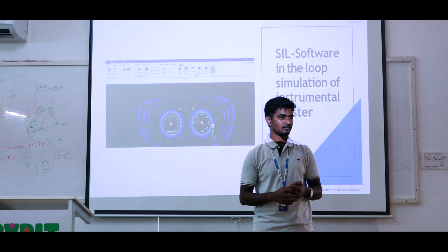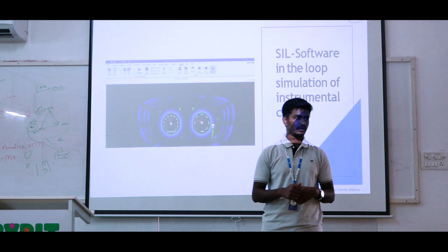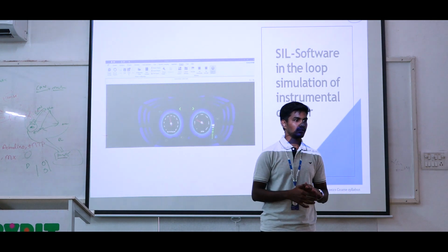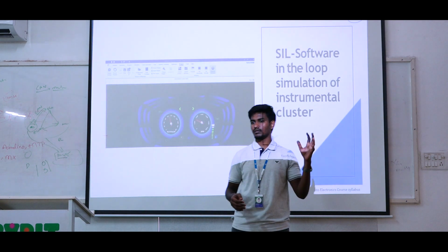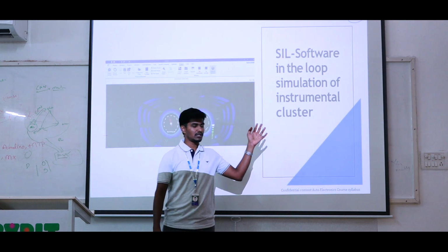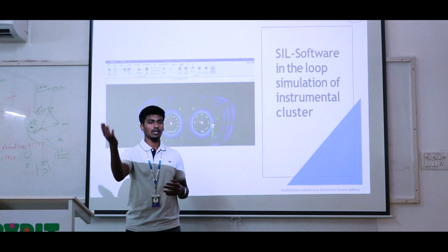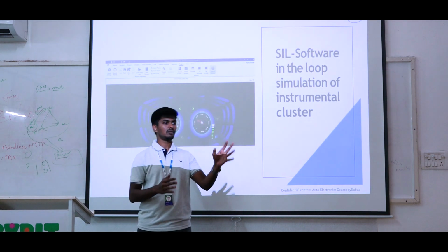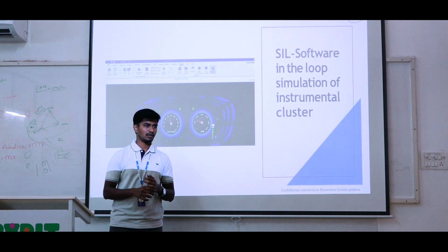Can we use the same CAPL scripting for MIL? No, it's not possible. MIL is a different thing. For HIL, same? Yes, for HIL you can use the CAPL scripting. What we did in the SIL means it will be getting some easy values, taking some decision, and giving the answer to the receiver. The same thing we can do in the HIL also. But for the model based, we don't need this kind of CAPL scripting.